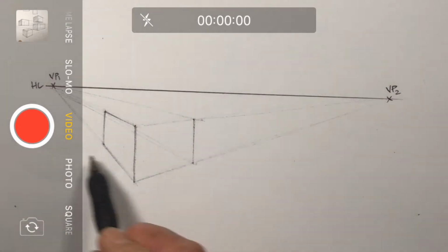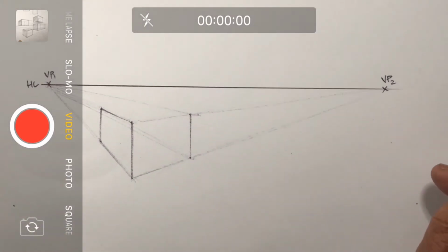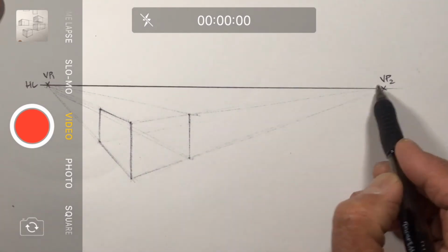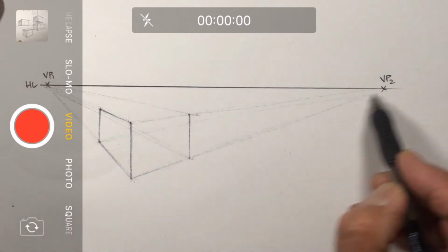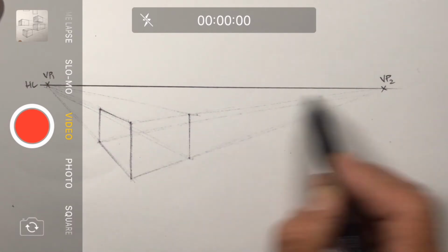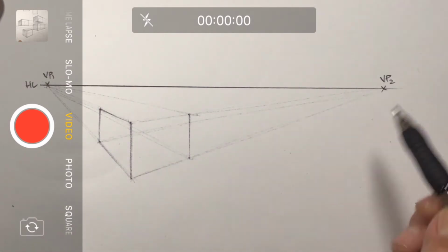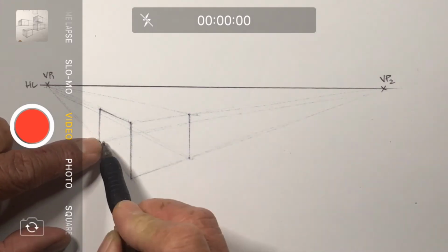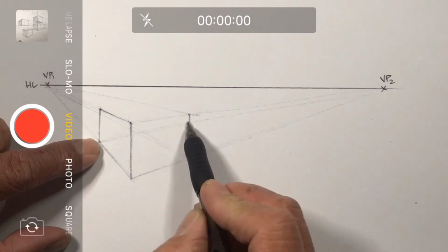With these 2 points, of course, they must project to the right vanishing point. Remember to ghost over the top, look at the target that you're trying to hit. And realistically, if you don't hit that cross, we really only want accuracy of that line to about this length.